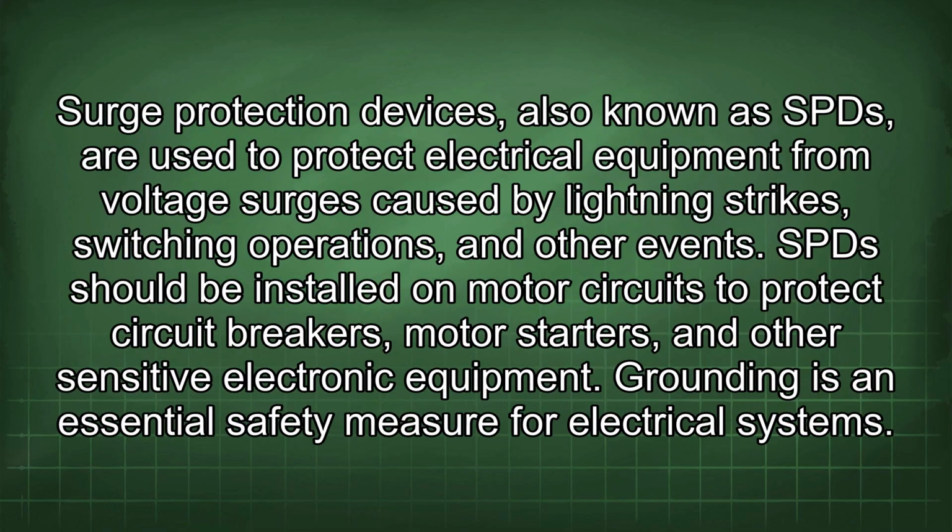Surge protection devices, also known as SPD, are used to protect electrical equipment from voltage surges caused by lightning strikes, switching operations, and other events. SPD should be installed on motor circuits to protect circuit breakers, motor starters, and other sensitive electronic equipment.